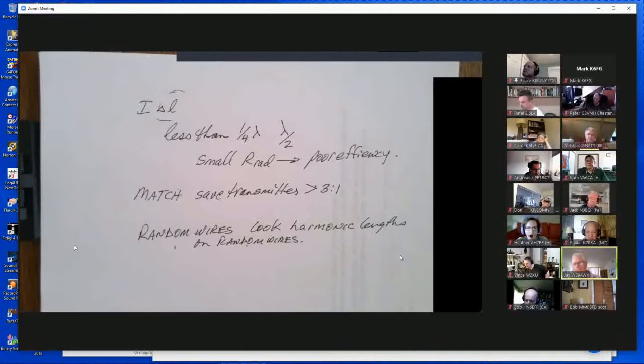Okay, you can get away with, I came out of broadcasting, and we used to, if you had 120 radials, you're basically putting them every 3 degrees. And that's overkill for most amateur situations.